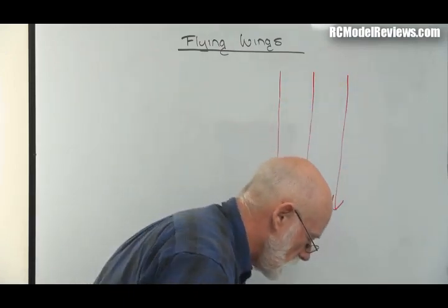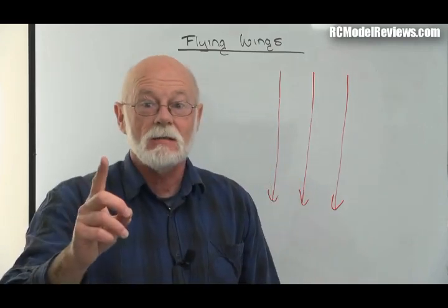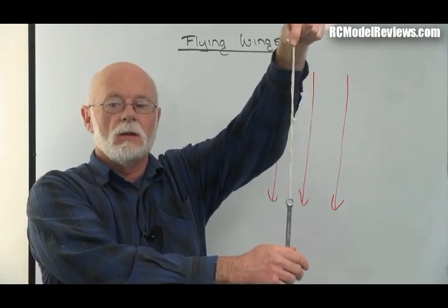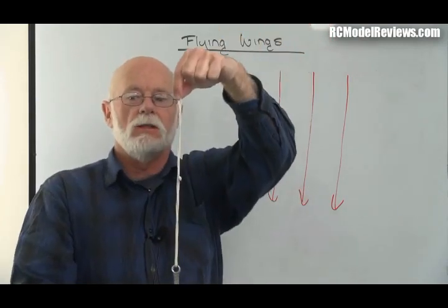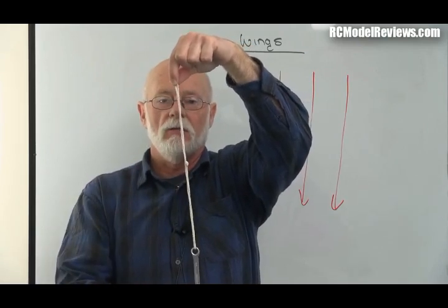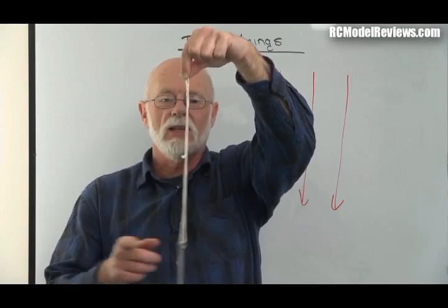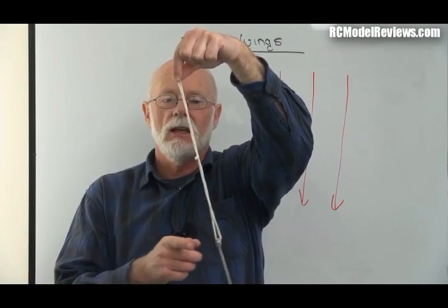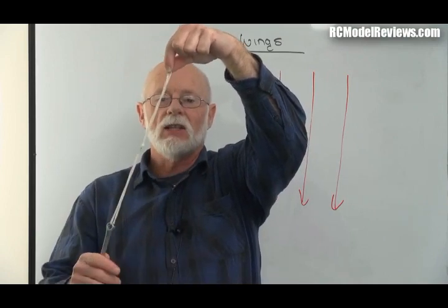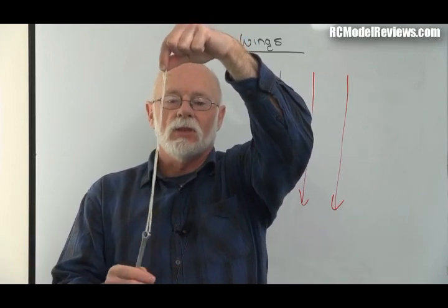And it's kind of like, I've got something I can demonstrate with. One moment, jump cut. That didn't take long. Okay, here we go. I have a plane, our model is flying straight into the wind. I'll put it in front of me so you can see. Flying straight into the wind, and it gets displaced. And it tries to go back to the original point, just like this spanner. But what does the spanner do? It doesn't go straight back. It's sort of woo, woo, woo. Eventually this oscillation will slow down and stop. But it actually has an oscillation. It goes one side, the other side, the other side. It's what we call a damped oscillation.